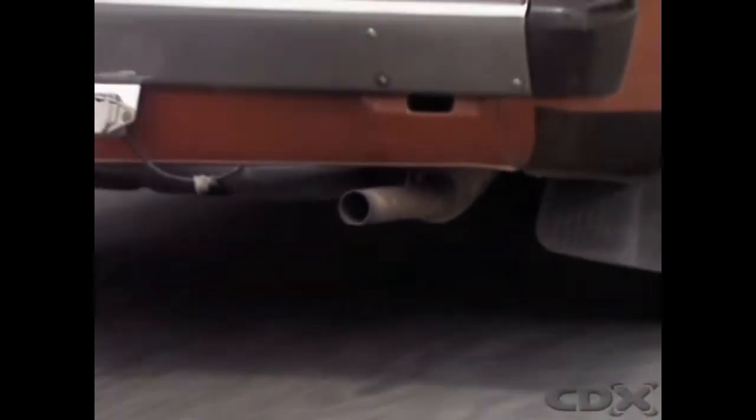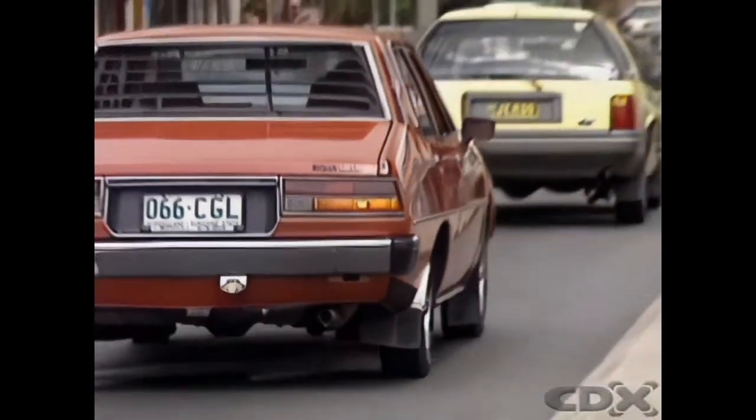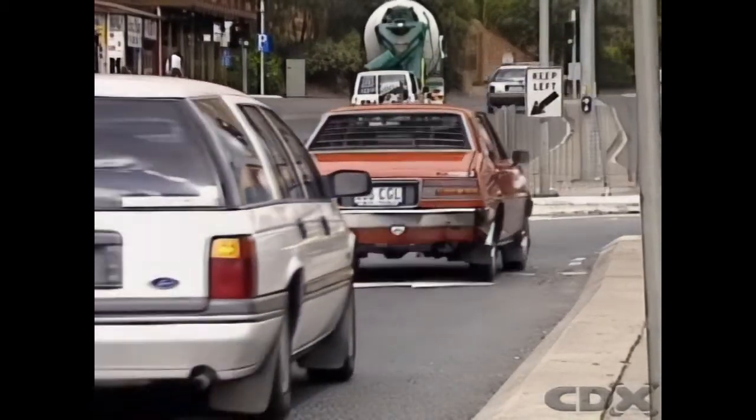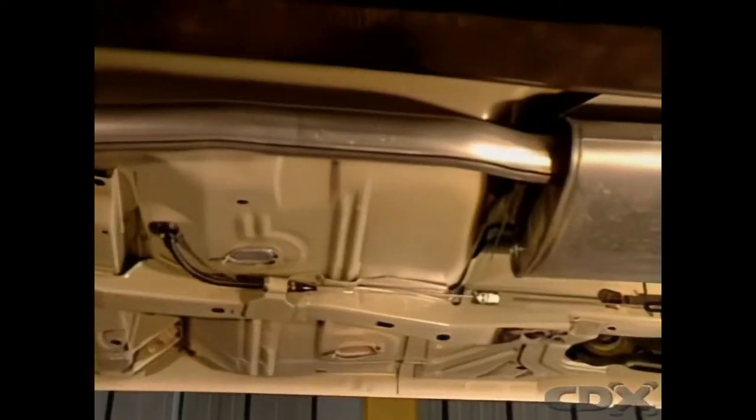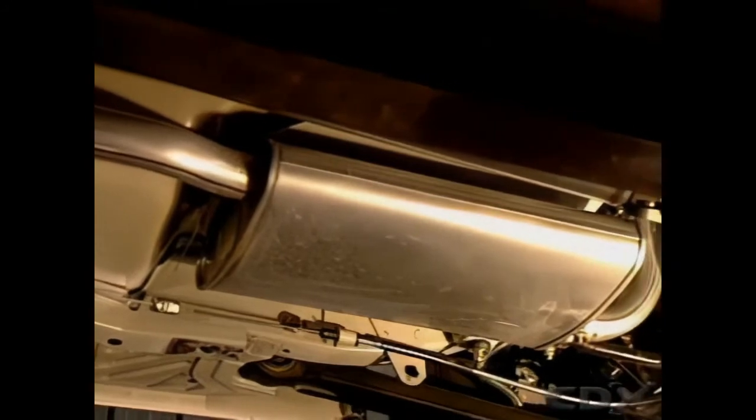The muffler slows down the gases and breaks up the pulsating sound waves and so reduces the noise. It must cause as little restriction as possible. Poor design can cause excessive back pressure that will slow down the escape of the exhaust gases and reduce engine performance.